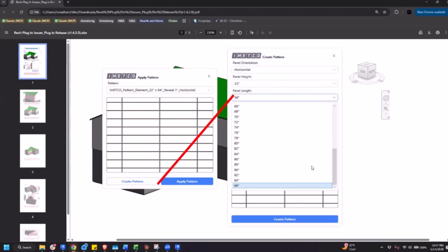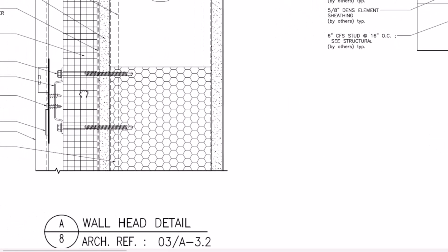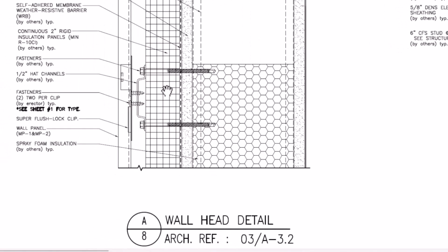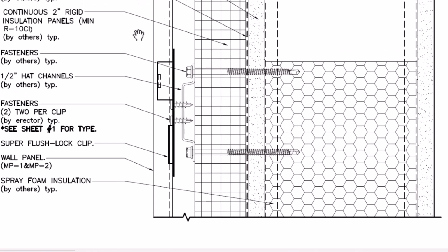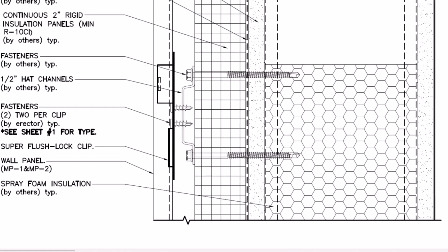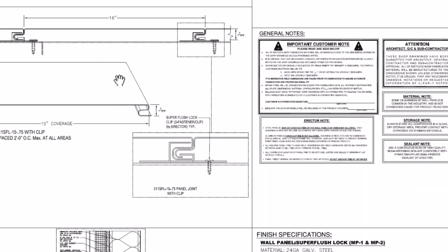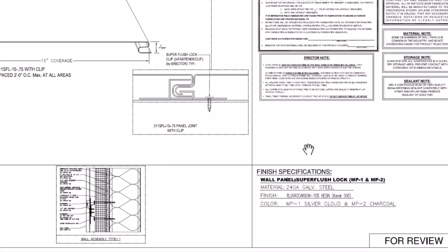So if you wanted this to be straight in the pitch, you usually have to move this prior to the whole step of everything else. It's the first initial step. The first step creates the pattern. The second step creates the lines of the pattern, you select it. The third step creates the panels. So you would have to align this on the first step after the pattern gets applied, before it turns into panels, because what you see here on the green lines is after the fact.